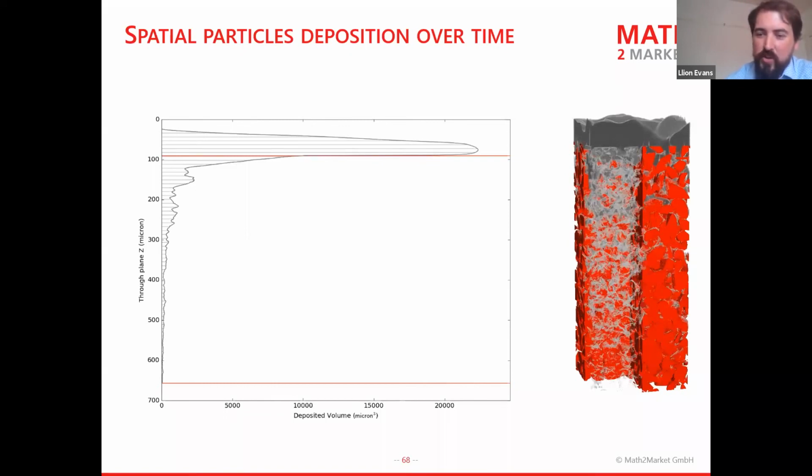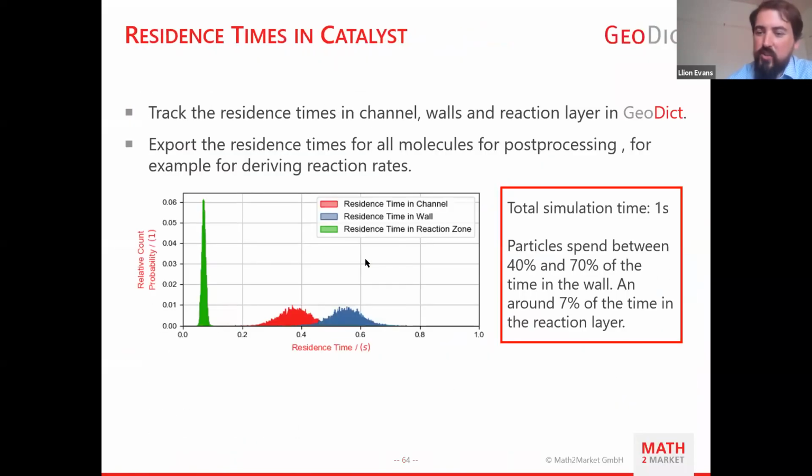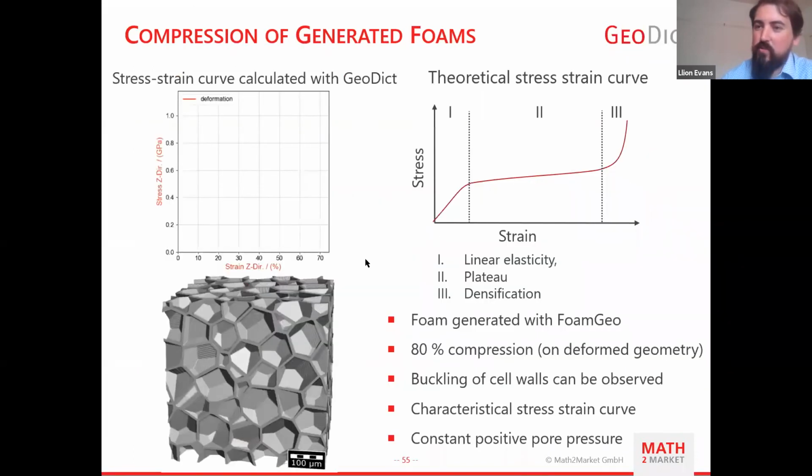During in situ compression of foams, I've usually seen a sharp drop in the load when the main cell walls collapse, followed by the usual increase due to densification. I didn't see this in your graph, and I was wondering if you took this into account.